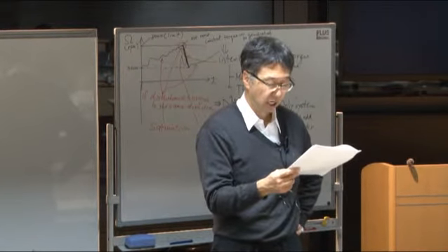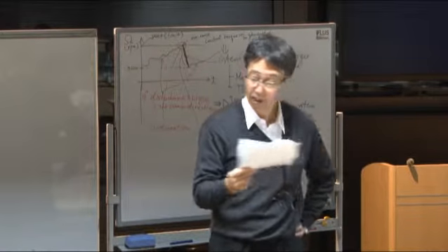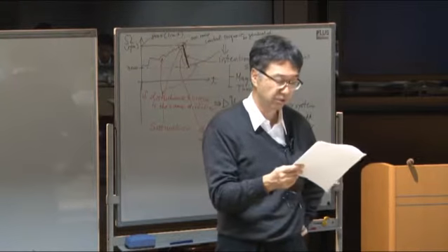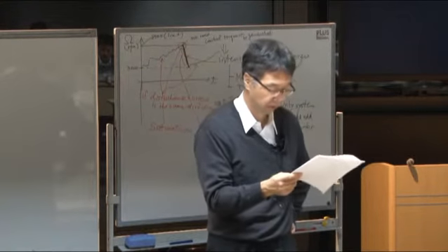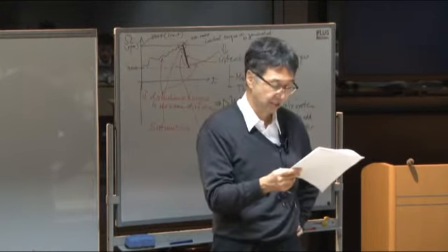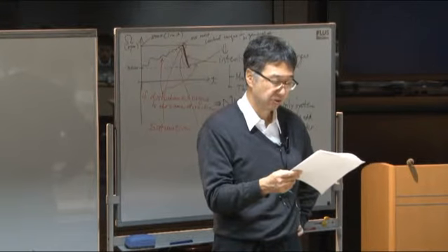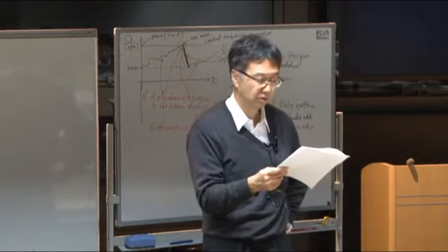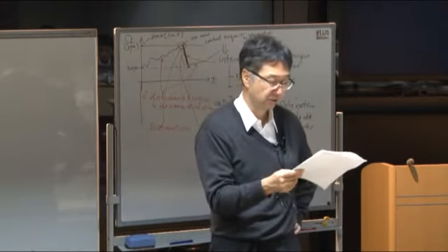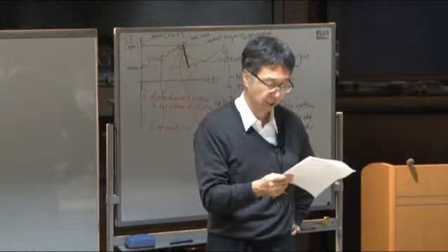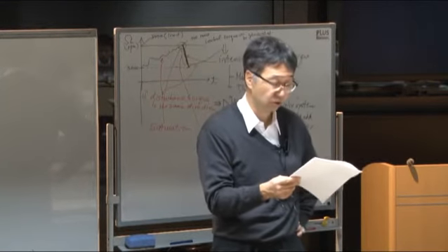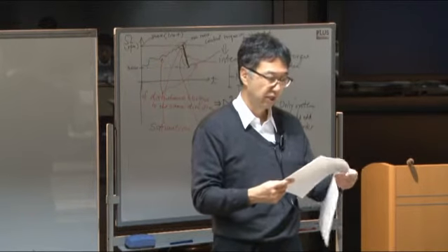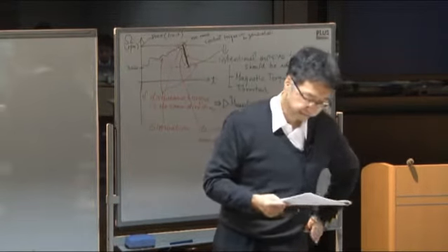Okay, and the onboard computer calculates some control torque using the feedback control law, and this torque demand goes to the control torque actuators, such as a reaction wheel, momentum wheel, magnetic torquer, or thrusters, and it gives some torque to the spacecraft. So this is a kind of control loop. Okay, and now go to the next page.